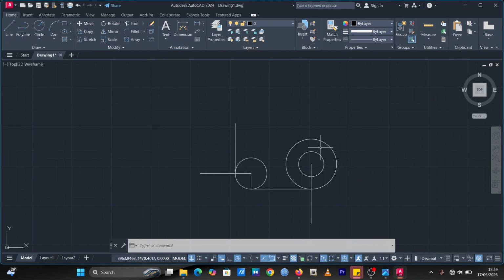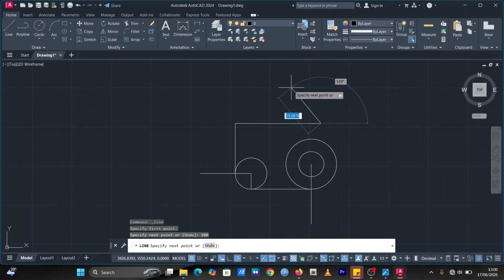So we are going to subtract 20 from 128, which is going to give us 108, to be able to draw that circle. So you pick your line tool, you stand here, and then you move to your right. You input 128 minus 20, which will give us 108. So you input 108, and then you press enter, then you press your escape key.